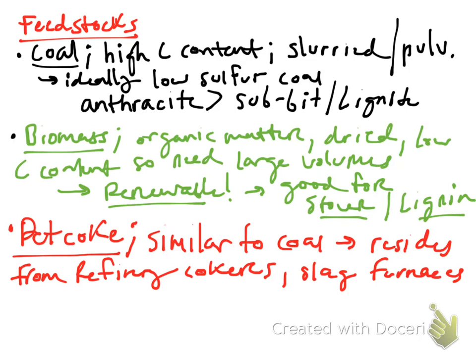This is a reason why gasifiers are advantaged to have at a refinery, because it can help continually upgrade that bottom of the barrel stuff, right? So where are you getting your cokes from? You're getting your cokes from vacuum gases and heavy oils and stuff like that, and so it helps refineries and petrochemical producers maximize the bottom of the barrel, if you will, all the way through, so they can actually have a use for this petcoke.